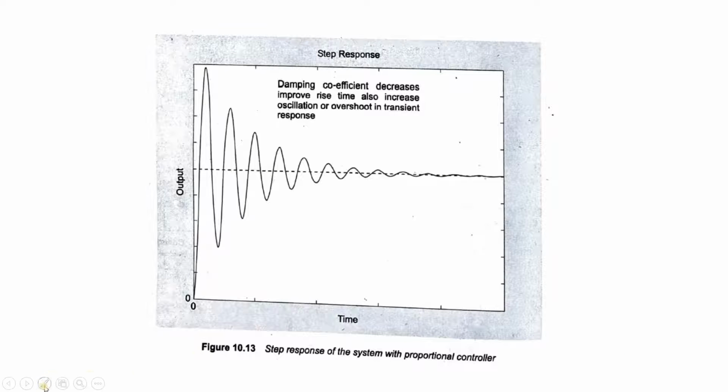But it was observed that if the value of Kp is increasing, because the error is increasing, it will result in excessive overshooting. The system will take a lot of time to settle down, and most importantly, it will never be totally settled down.